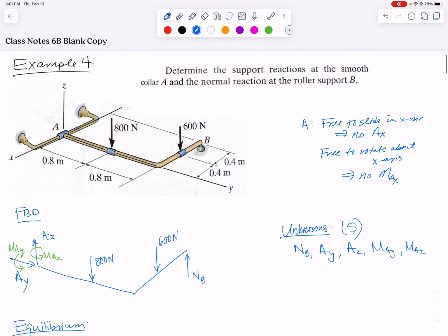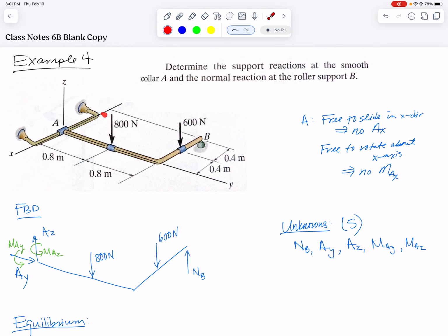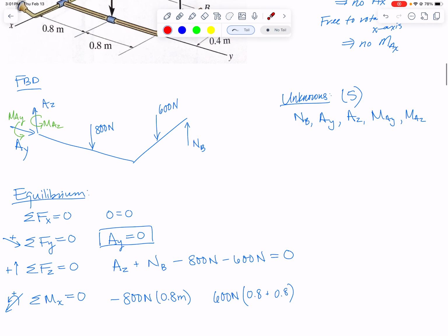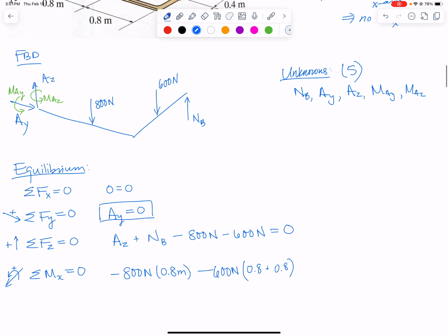And that one looks like it will also be negative. We start at the axis, go out here, and the force points downward, so we're going to be rotating that way. Thumb would point in the negative x direction, so also negative.